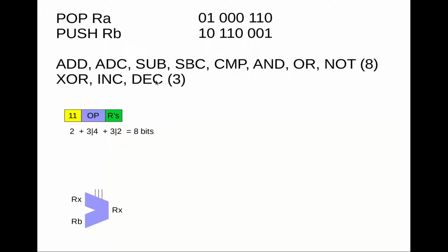And so I've taken the decision to also implement these nice to have instructions. And the consequence of that is that I need 4 bits to encode the operation, and that means I only have 2 bits to encode the single register that I want my ALU to operate on, the other one being the B register.